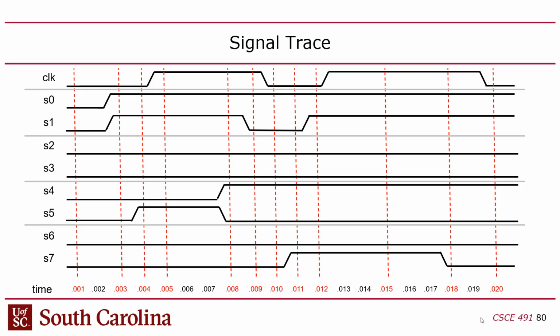Now the thing though is, there's really no point, and when we first developed this it was kind of a thing we talked about, there's no point in sampling using a fixed sampling period. It's kind of dumb to do that. Because if the signals don't change, there's no reason to write the values of signals that aren't changing, right? So in the signal file, the samples are not uniformly spaced out. It doesn't have a fixed sample rate.